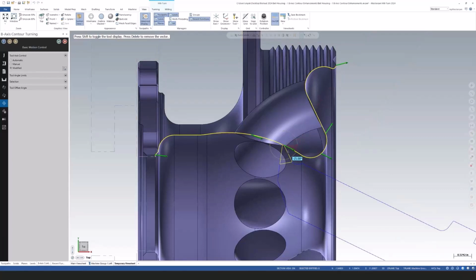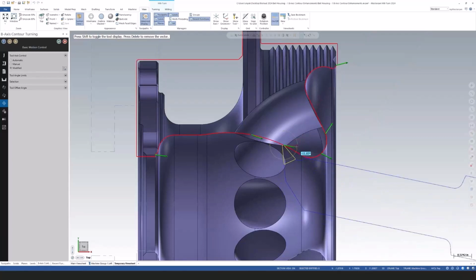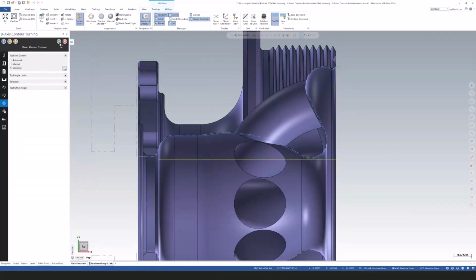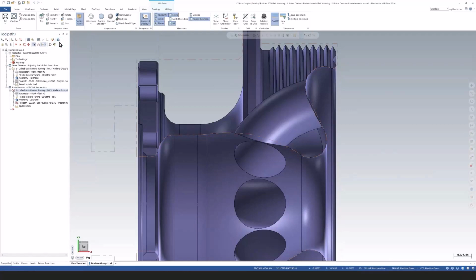For this one, it shows red, right? It highlights very solid red everywhere you have a problem if you run into any interferences, but everything's looking pretty good on this guy. So we'll go ahead and finish that out, click OK, and regenerate the toolpath and verify it. Hopefully, we didn't even explore further down into that part, but because we're using the modified, it should just be defaulting to the automatic approach. It's going to do a nice job of cleaning that up for us.